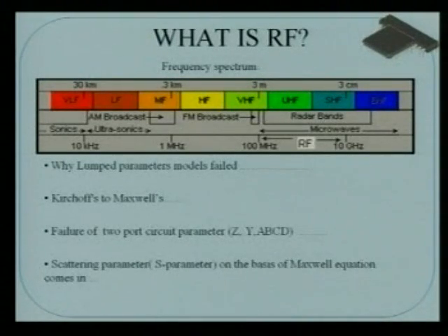But what happens when the frequency goes up in the gigahertz range? Then the wavelength goes down, and when it is comparable to the size of the components, there will be a lot of reflections and a lot of mismatch, because ultimately you will find there is a phase difference along the length of the component, and that creates the challenge of whether Kirchhoff's law is still valid or not.